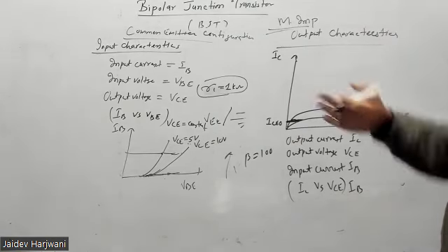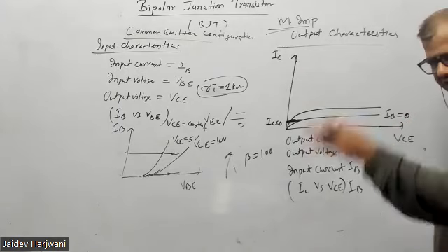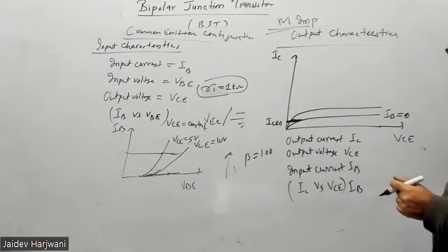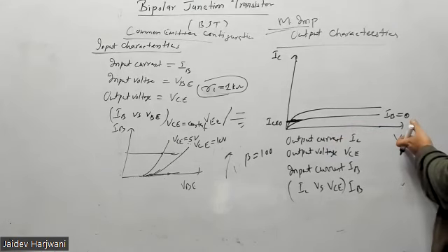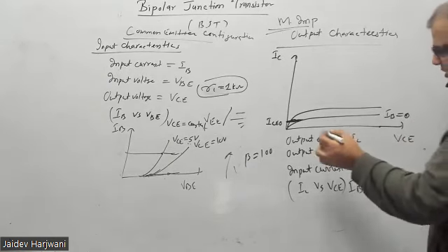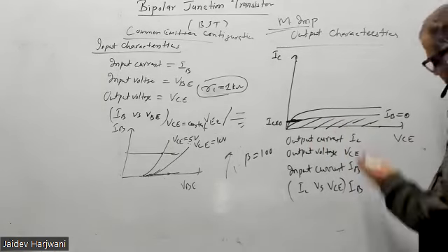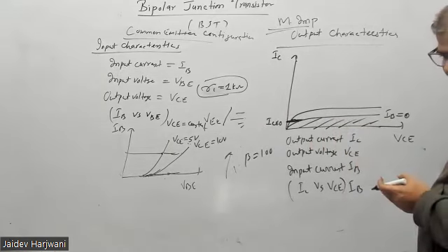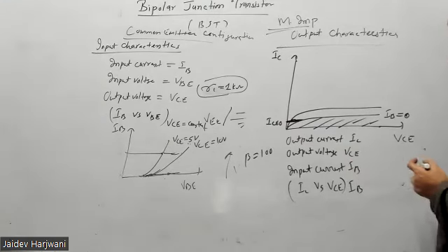So that junction become reverse bias. Either 0 you make negative, that input become reverse bias, and output is already reverse bias because you're applying VC positive, NPN transistor. N means negative, VC positive. So this is already reverse bias. So this region become cutoff region like previous year. Okay. Now VC cannot go negative. Okay, VC cannot go negative. So VC has to be like this only.